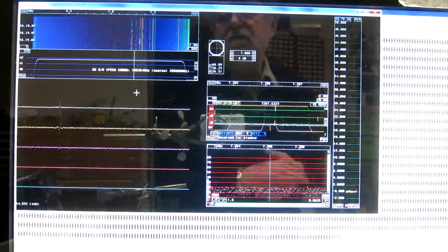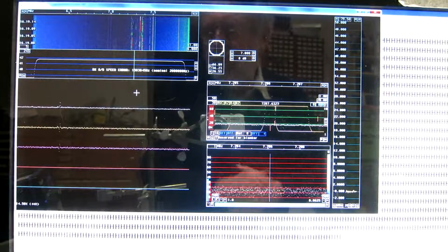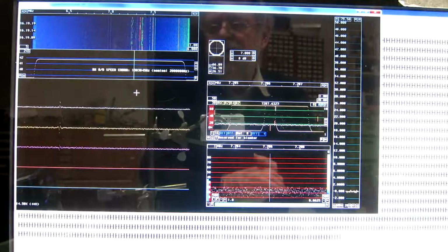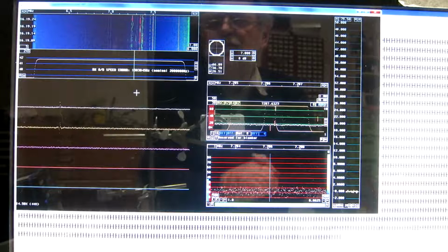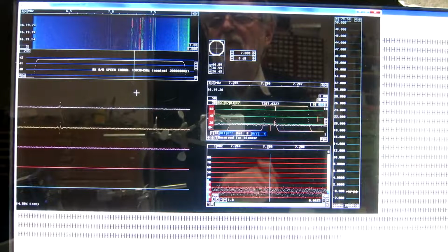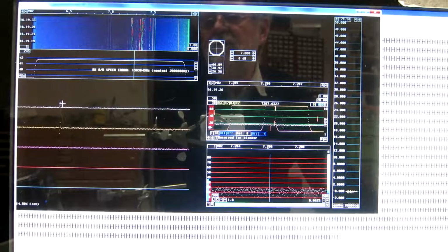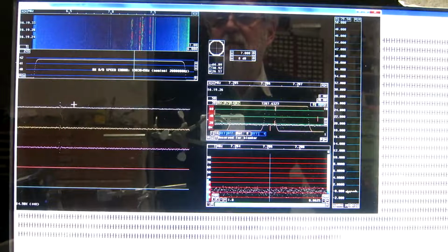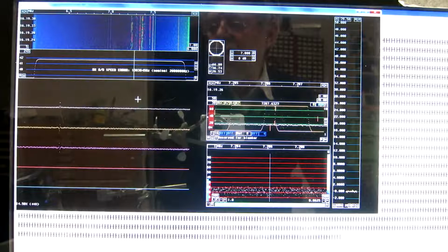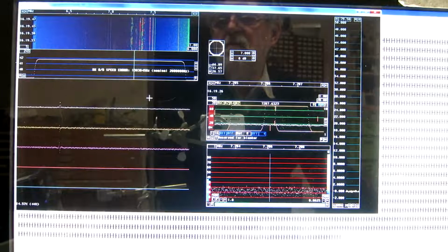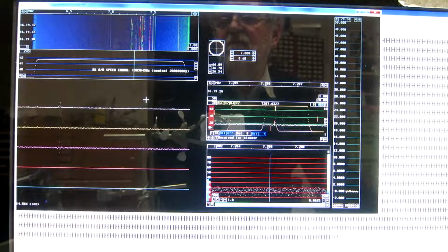I have done the calibration with the function generator in a way that isn't really correct. That is because I wanted the strongest possible signals, so it would be possible to study the small remainder that we have when the blanker is running. But there is an error, and that is that the input impedance of the SDR-IP is not 50 ohms. And feeding it through a small capacitor means that the signal varies with frequency.